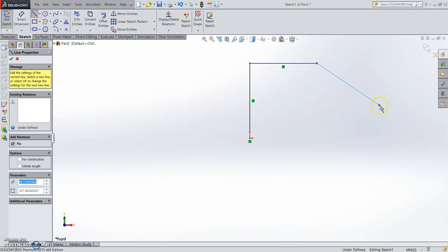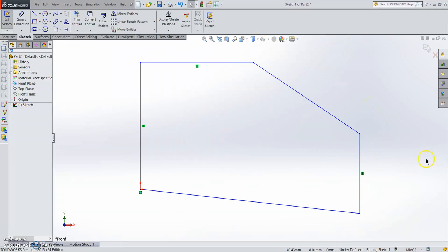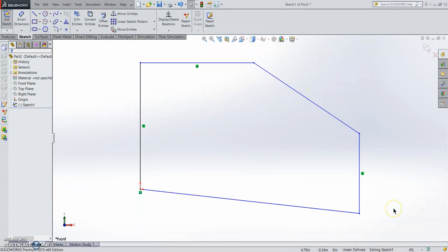and I will just draw the pattern, so it doesn't need to be exact basically. So press the F button. So roughly the pattern is like this. And if I want to do a dimension right now, I have to choose the unit down here correctly. So I'm going to choose the inch, because the drawing that was shown to us is in inch. So now it is in inch. But when I come to changing the unit, we are jumping out of the sketch environment. So right click over here, choose edit, and we go back to the sketching environment. So now this is the thing.